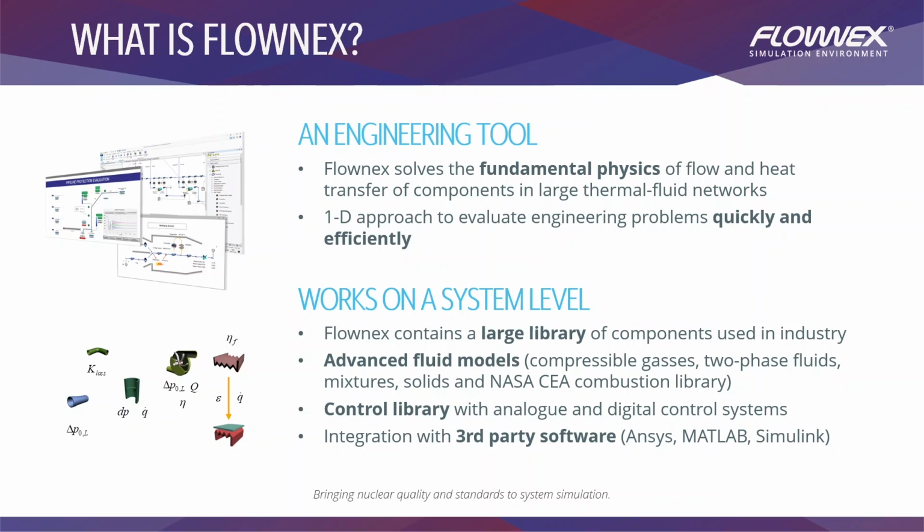So, where does Flownex come in? Flownex is an engineering tool that can be used by engineers in the design and analysis process of thermofluid systems. It solves the fundamental physics for flow and heat transfer components of large thermofluid systems. Flownex houses a large library of standard components used in industry, advanced fluid models, a control library, and integration with third-party software such as ANSYS, MATLAB, and Simulink.